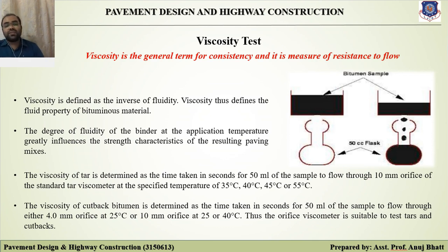Many researchers believe that the grading of bitumen should be by absolute viscosity units instead of the conventional penetration unit. The degree of fluidity of the binder at the application temperature greatly influences the strength characteristics of the resulting paving mixes.